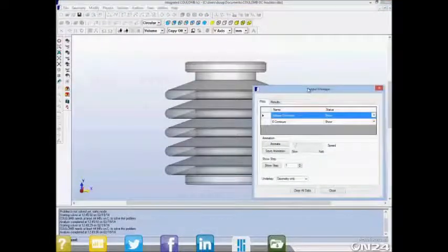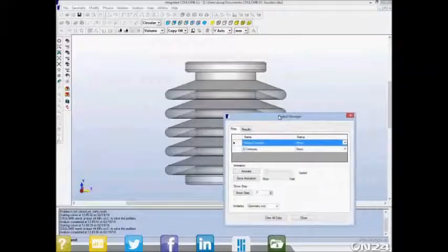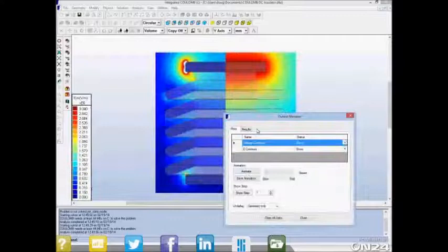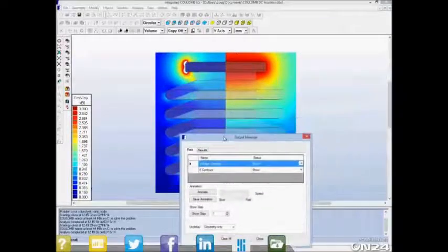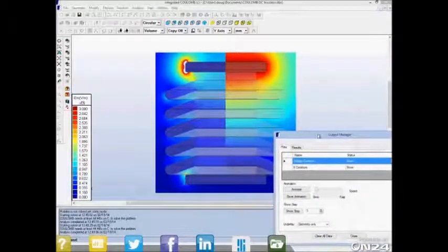So with the output manager, we can examine and contrast both its solutions. Here is step one. This was the permittivity solution, where again the voltage drops mostly near the high voltage, and as a consequence you don't see high fields running down the edges of the insulator.